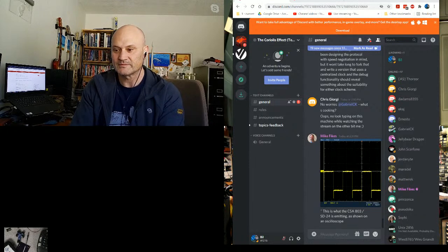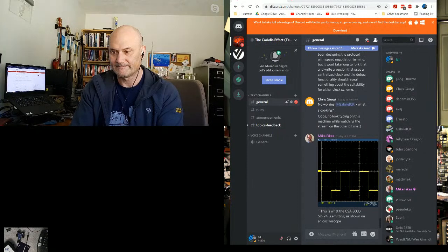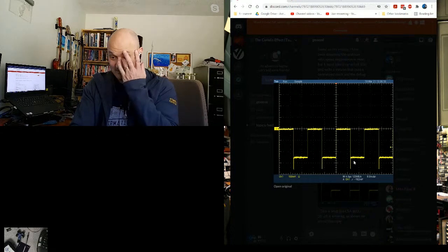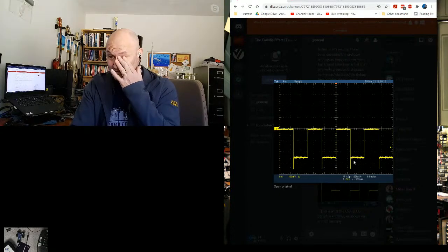Right. So Mike posted what happens when you stick... I don't know if you can see this. Can I click on it? Oh, there we go. That's what the output of the TDR looks like going into a scope. And actually you see a little... Hey, Mike, can you try that again and set your scope for 50 ohm termination? Or is it already set for 50 ohm, would be my question. But this is what the TDR looks like in the macro time domain.